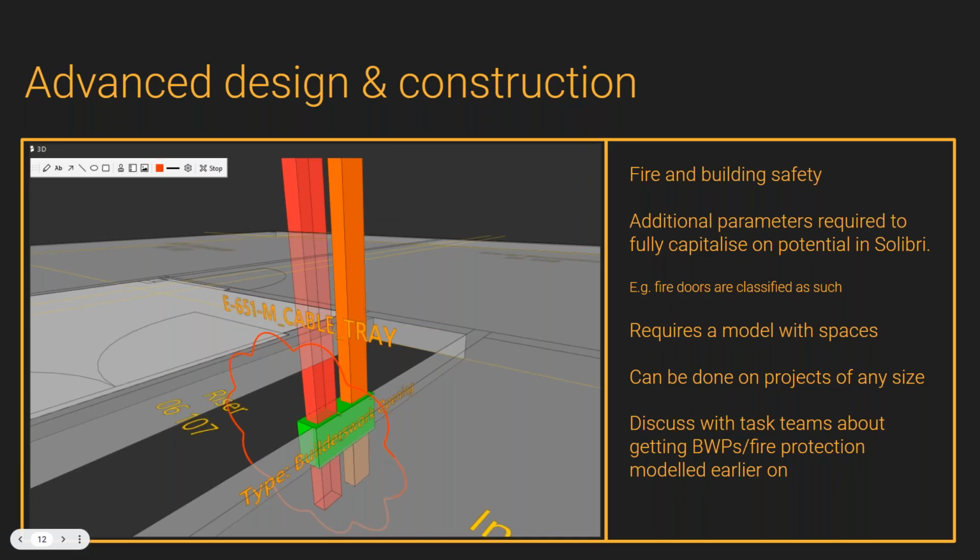Now, first of all, there seems to be a systemic challenge, again, at least in the UK. These exercises need to be done as early as possible. So we're talking mid to late stage, RIBA stage 3. In the UK, I don't think I've ever had builders work openings available in a model until mid to late stage 4, which isn't early enough to provide the best value for us.